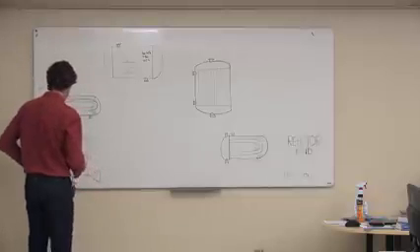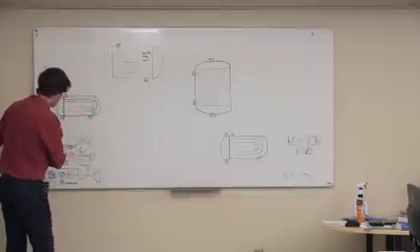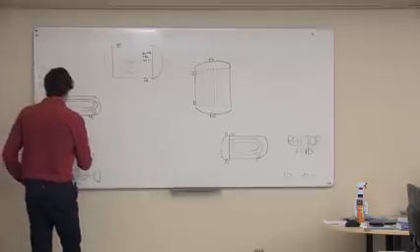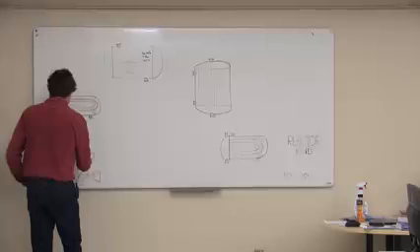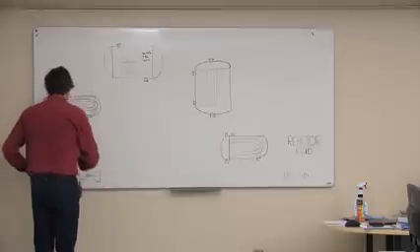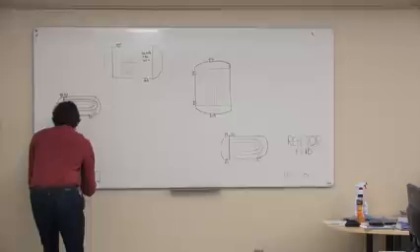Most of the time, in terms of the piping now, you'll want to know what the pressure is on the inlet to the pump. You'll want to know what the differential pressure is. So most people measure the inlet pressure by putting a PI in there. So we need to do that.